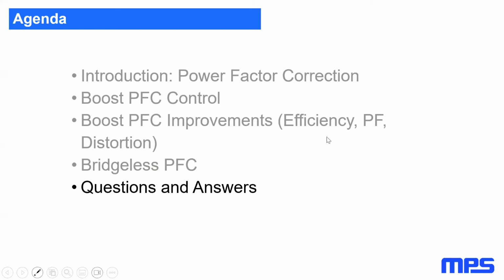Okay, thanks a lot. The next one was also referring to the bridgeless PFC. For this below 1 kilowatt converter, why not use a conventional boost converter? Well, the answer is really in the slides: to get higher efficiency. It depends, of course, on the application and the requirements, because this will tend to cost more.